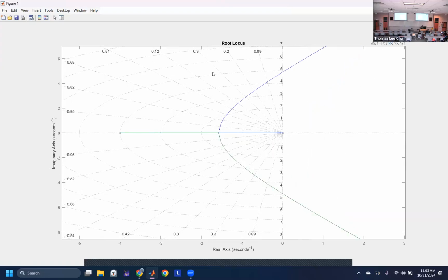Because we're looking at the closed loop poles, I think it was 0.358. So we see 0.3 and 0.42, so it's going to be between these two sector lines. And I just pick roughly where I think 0.358 is, which is roughly there. Close enough, it's 63. Last year I had a ton of time, so I got the exact value of 0.358, and it was 63.3. That's how I found it. So there we go, I'm going to stop sharing that.